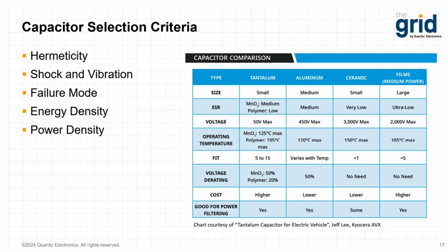Now, moving along, shock and vibration is another area of concern. For example, in avionics systems, the electronics on board, which of course include the capacitors, are exposed to high levels of vibration, particularly in the case of, for example, rotary wing aircraft like helicopters. Today's modern airborne platforms and even space-based platforms introduce a lot of vibration to the individual applications, and the capacitors must be able to withstand some aggressive shock and vibration conditions.